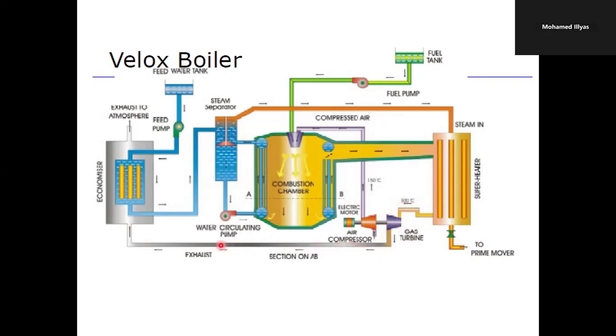And then the gas is supplied to the economizer. So the economizer has the provision to get feed water from the feed water tank. The gases passing over the economizer tubes will be heating the water before entering into the boiler here. The preheated water enters the steam separator,